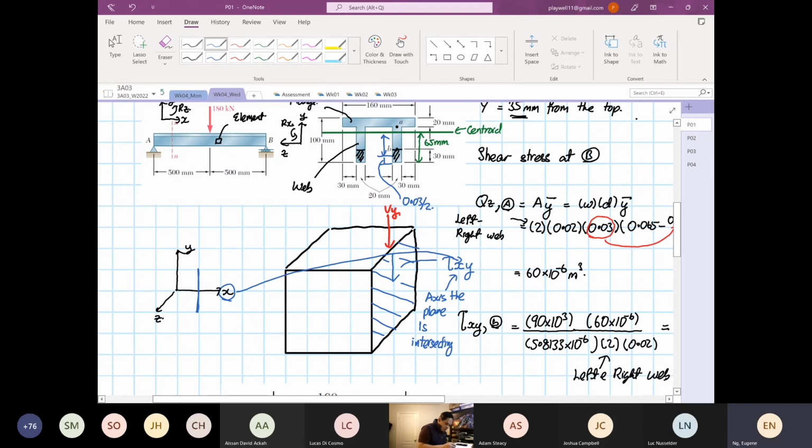So that is what this x is all about. The y over here is basically the direction the shear force is pointing. It's in line with the y-axis, so that's why I call it y. And because of equilibrium, we have to have a counter over here. So this is our shear yx, and therefore the shear xy has to be equal to the shear yx.